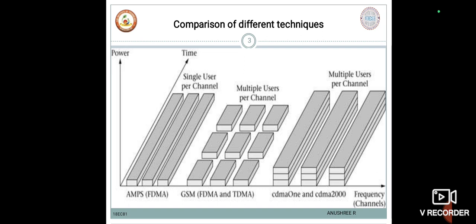This process has the effect of demodulating the signal intended for the receiver while rejecting all other signals as broadband noise. Since a specific minimum level of signal to noise ratio is necessary to provide a certain level of received signal quality, the level of background noise or interference from all the system transmissions ultimately limits the number of users of the system and hence system capacity. Therefore, these CDMA systems are carefully designed to limit the output power of each transmission to the least amount of power necessary for proper operation.